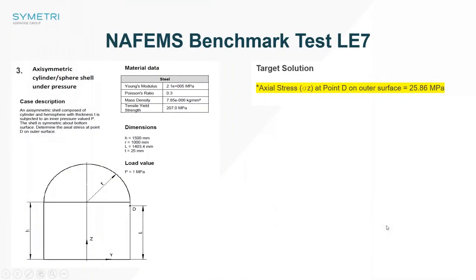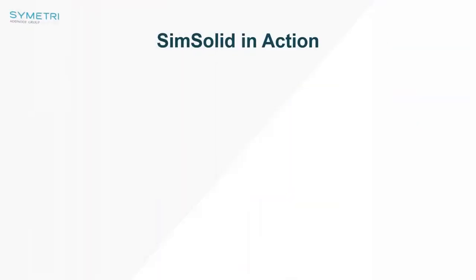Now this is a hemisphere example, and we're basically going to pressurize it. Typically when we're doing pressure vessels or spherical shapes, we normally use it as a quarter model or as a 1/8 of a model for stability. But in this example here, I'm going to take the whole shape and try to use inertial relief to be able to determine the results. So let's just go through that process.